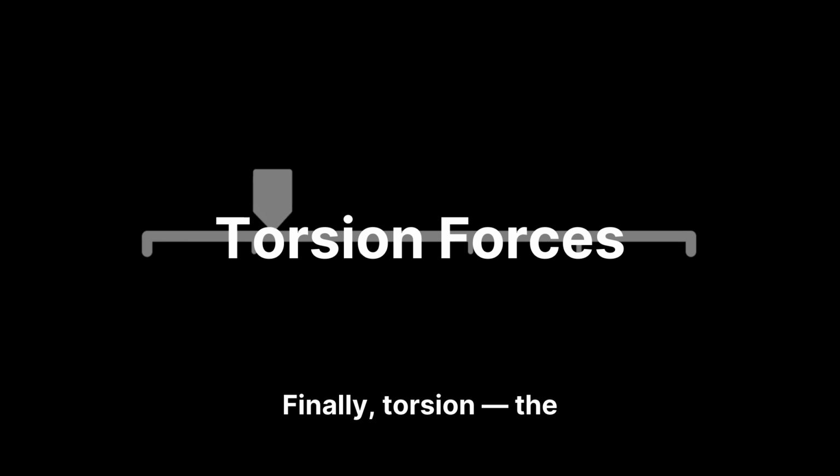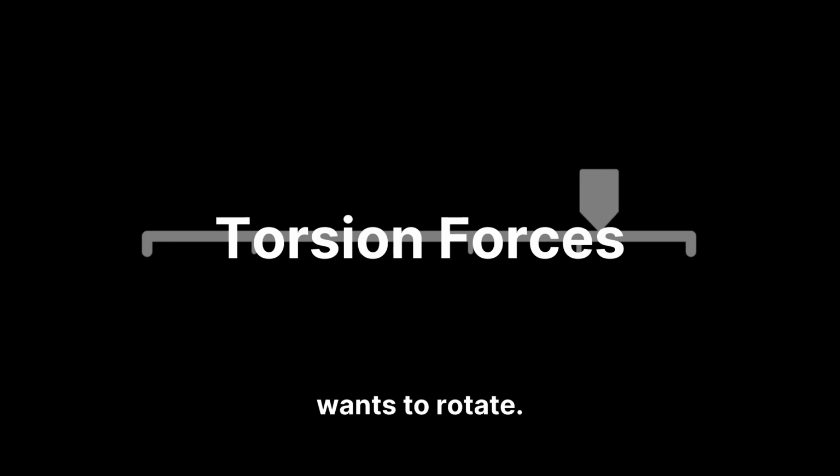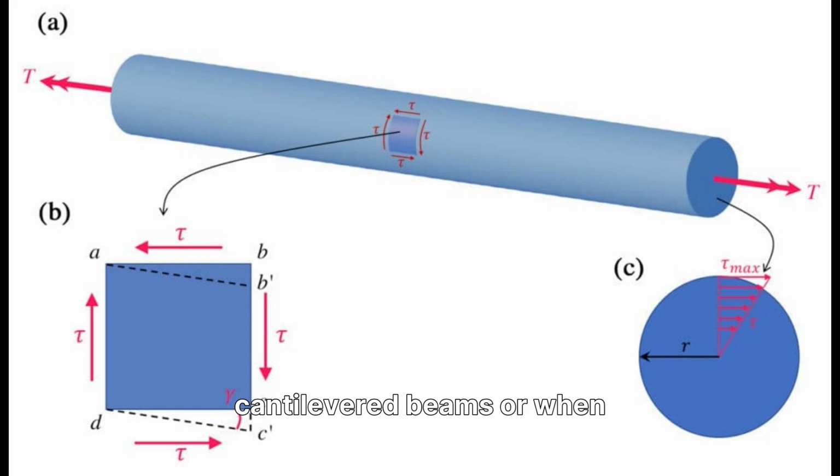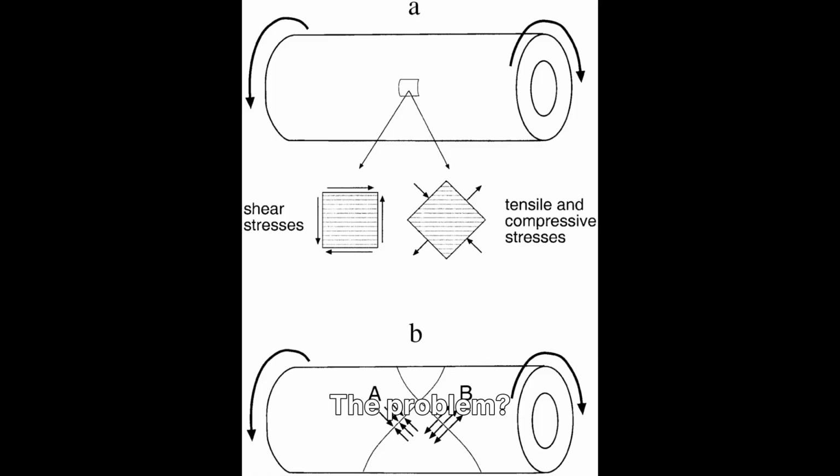Finally, torsion, the twist. Whenever a load is applied off-center, the structure wants to rotate. You see this in cantilevered beams or when part of a structure sticks out with no direct support. Torsion causes the beam to twist along its axis. And while some torsion can be relieved through other load paths, primary torsion, the kind that's essential to stability, must be resisted directly. The problem?